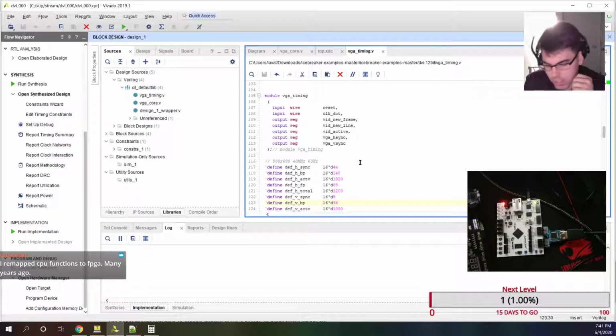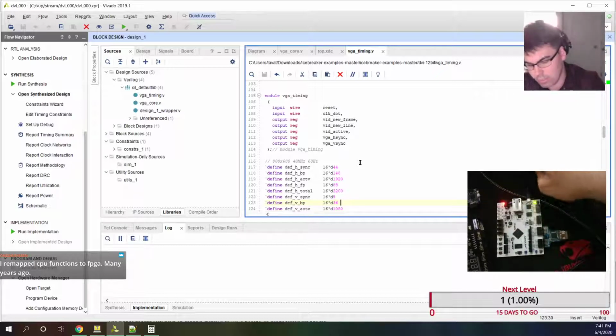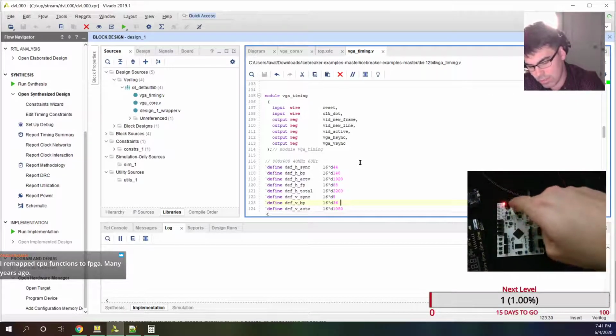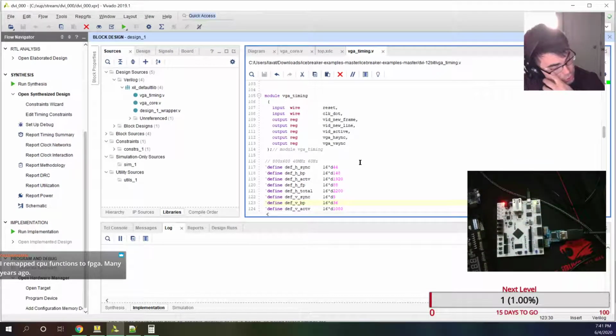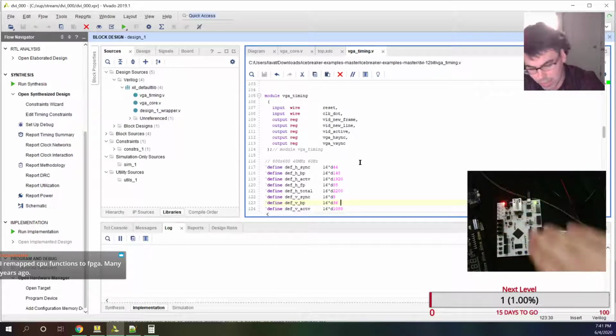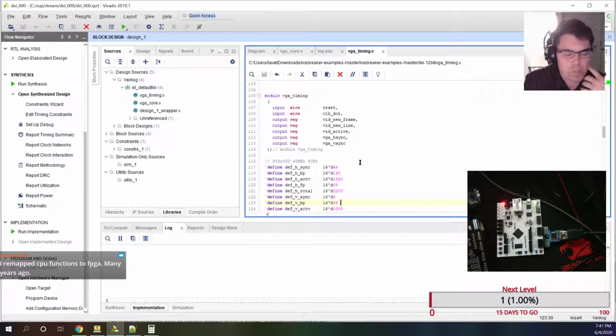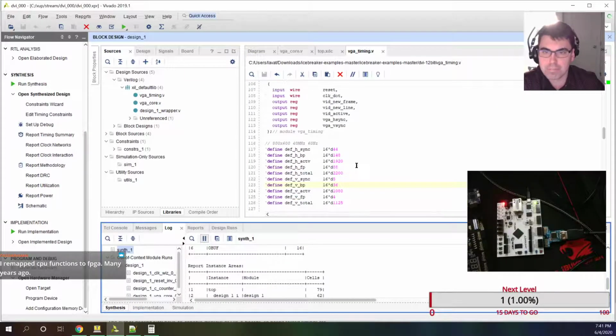The goal here is to have Ethernet UDP stream a video here. We're going to process the video in AXI stream format, output the video over HDMI, and also output the video back over Ethernet. We may not be able to do 1080p effortlessly over the FPGA, but we'll have to see. Oh, we're going to get the right bitstream state. We'll find out if this works or not.